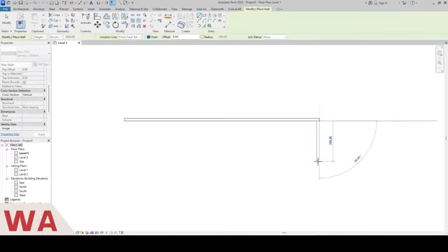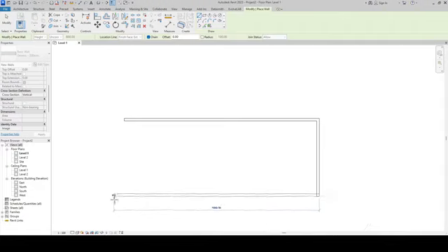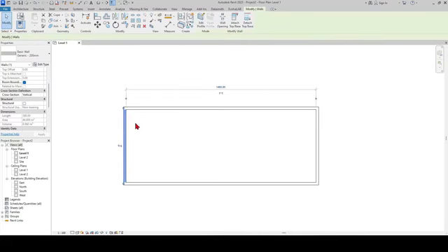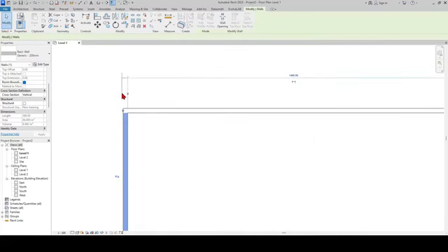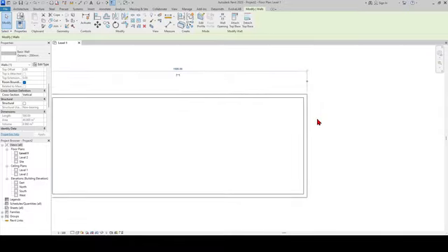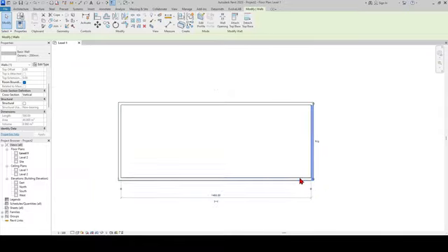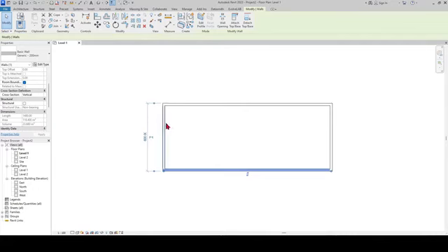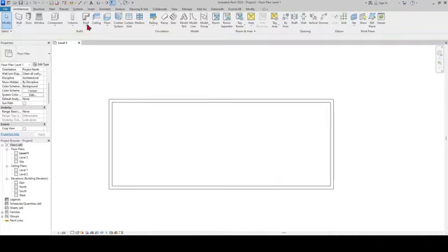We re-enter the wall command. When the walls are an equal distance apart, it automatically detects this. We can adjust the reference values by dragging them to the desired position. Unlike AutoCAD, Revit automatically detects that the line we draw is a wall and gives it a height, making it a 3D object.